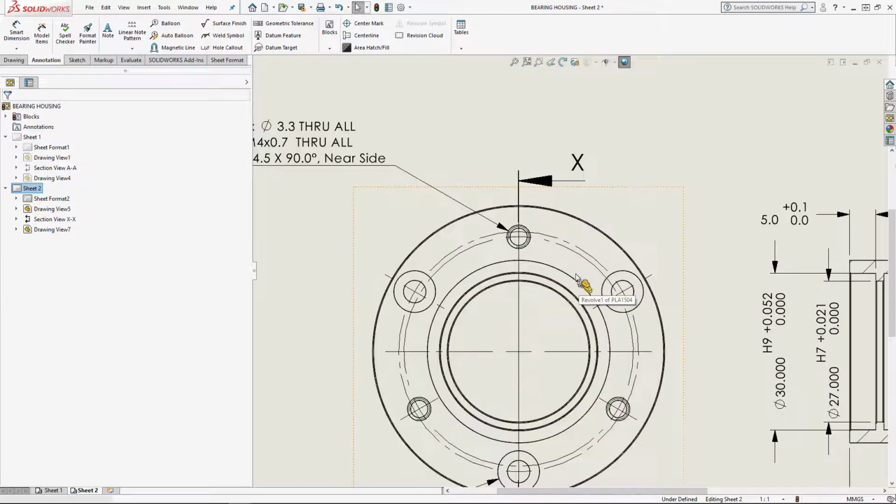Now because these holes, these larger holes, these counterbore holes, are part of a circular pattern, the system's taken the liberty of putting this collection of center marks in. So I'm highlighting it in orange. And those center marks have angled center lines that go through those counterbore holes that reflect the fact that it's a circular pattern. So they're all angled towards this center point.